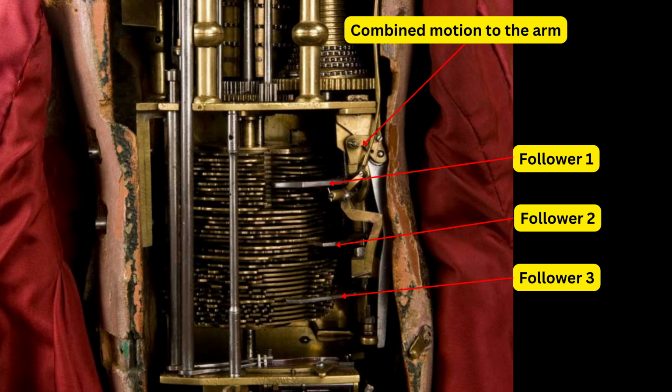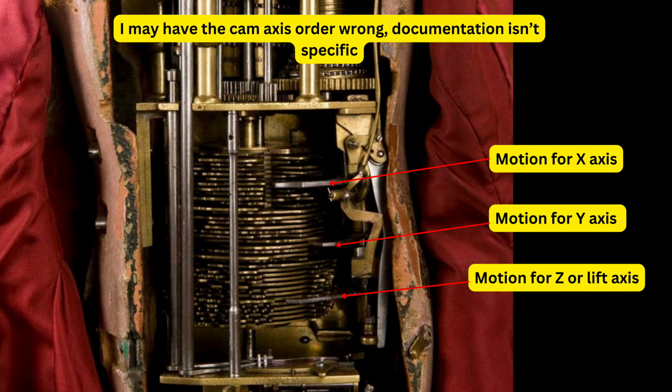As the machine writes, the cam stack moves, not the followers. The followers stay essentially fixed in position, continuously pressed against the cam cylinder by springs or their own weight. When the machine finishes a letter, the indexing system below, the disk with the adjustable wedges, acts through a system of levers to translate the entire cam cylinder laterally, effectively up or down along its axis.